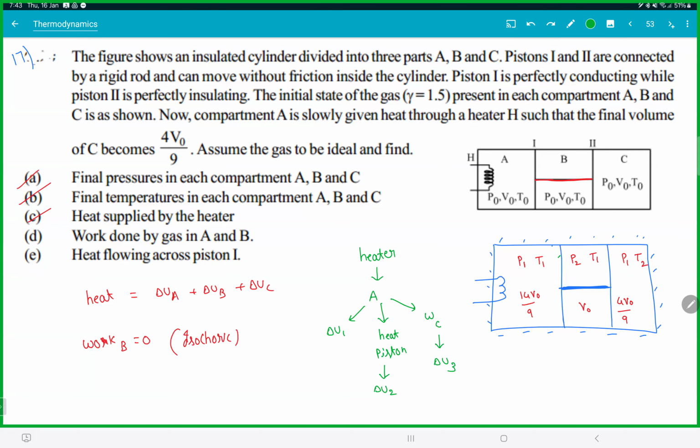Now in the first compartment, you want to find the work done, integral PdV. How will you do that? Do you know what process is there in the first compartment? Vihan? You don't know what process. You can't use P delta V. Pressure is not constant. We don't know what process is the first compartment. We can't solve. But look at this distribution. It makes your life so easy. It clearly tells you where the energy is always getting distributed. Please check out the thing in the green one. Ask me if you're confused with that.